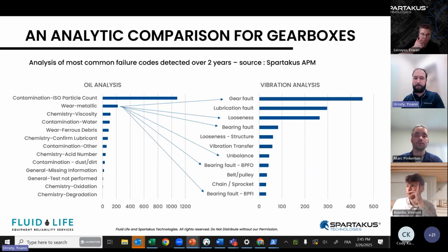So it's really about assets degrading themselves, and parts and components, right? Some of the steel, some of the copper material and the coatings of the rotating components are going to degrade, and you're going to be able to confirm that with vibration analysis and isolate where that comes from, right?